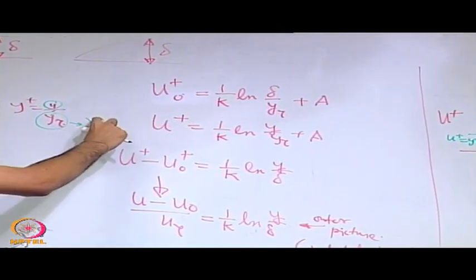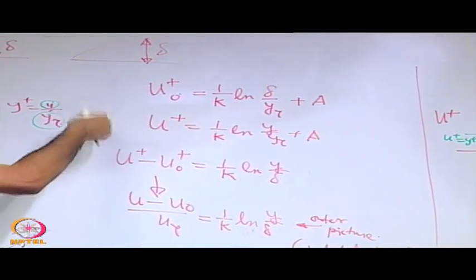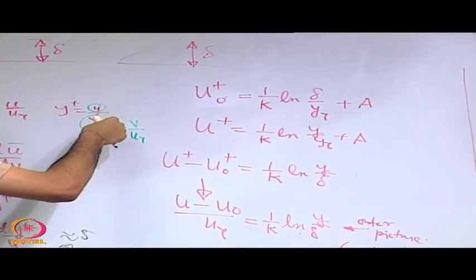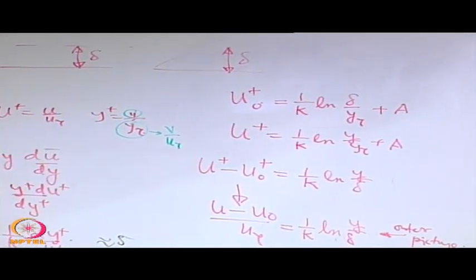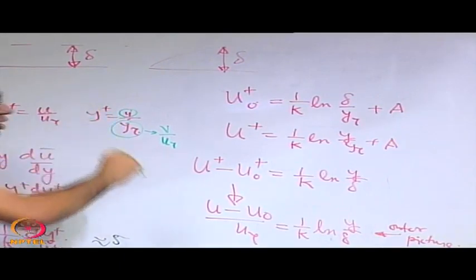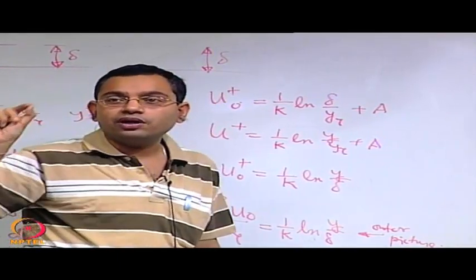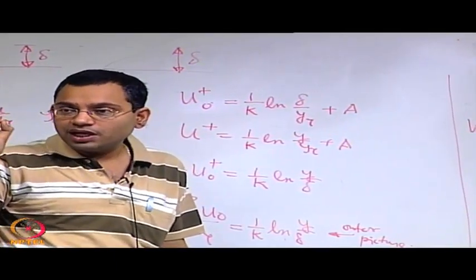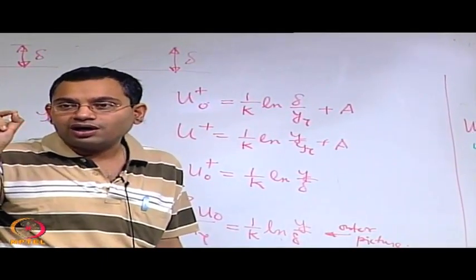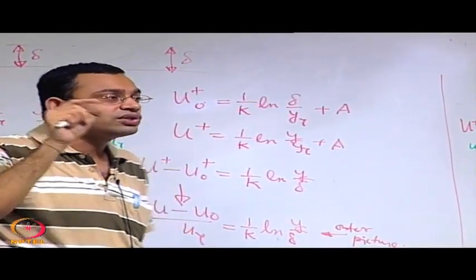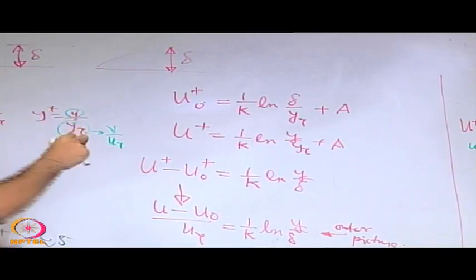So this ratio is small, so when y is divided with it, it blows up y. So what it does, it gives a new length scale which zooms or blows up the phenomenon very close to the wall. Because this behavior is valid very close to the wall, you do not have sufficient resolution unless you zoom it up or blow it up with a stretching.